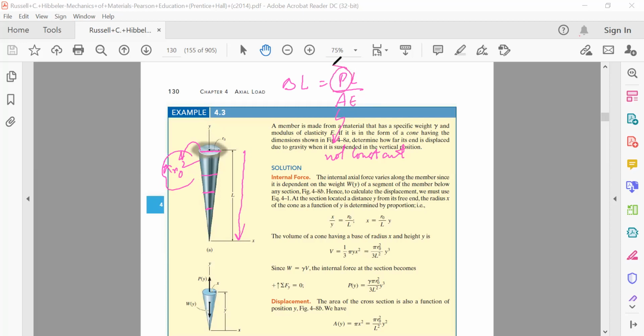Number two, talk about the load. The load acting on the machine element is the gravitational weight. Now if you take a section out here and consider this much amount of the material, this amount of the material will have some weight. Let me suppose this portion has weight W1. This W1 weight will be pulling the upper portion downwards. That is, the weight W1 will act as the external deforming force for this portion of the machine element. Now as you go up and take a section here, this much amount of the weight will come in.